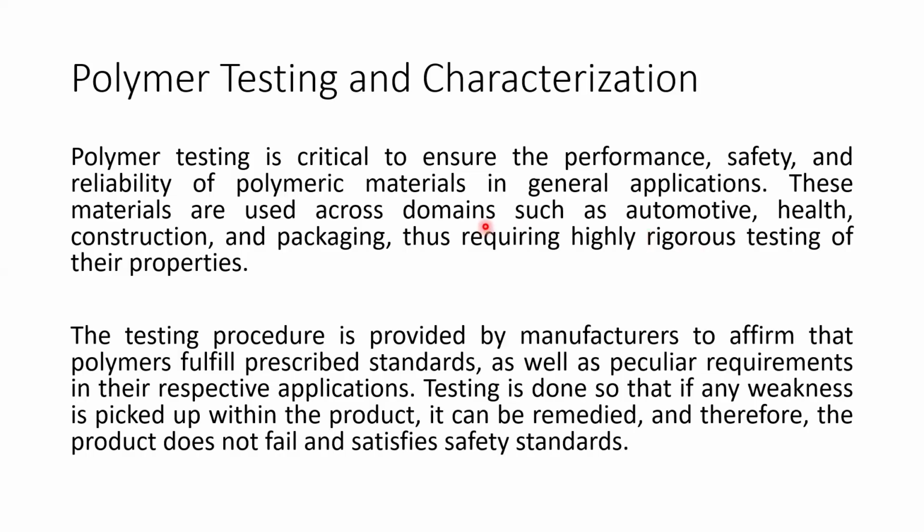For example, for space applications in ISRO or radiation resistance applications in DRDO, they put the polymers in an accelerated radiation dosage chamber, where they find out how much time, temperature and radiation conditions apply. Everything is put in one chamber and given an accelerated dosage of, say, 10 years. So how much can the polymer withstand for 10 years or 20 years? That is the idea behind polymer testing.